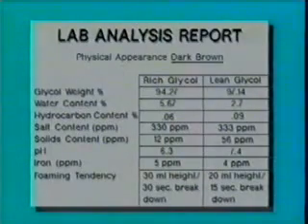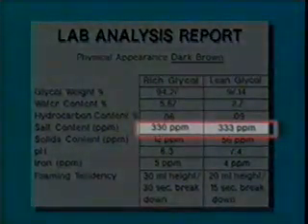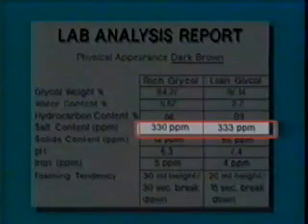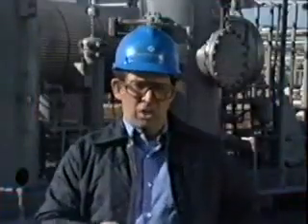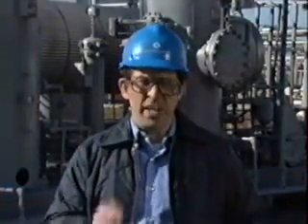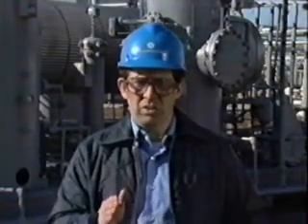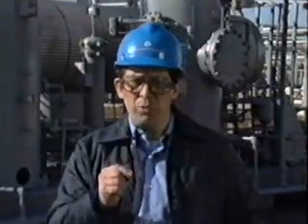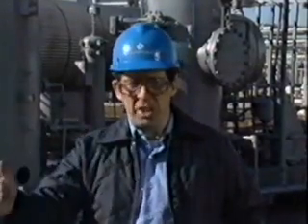Although the salt content of our samples is a little high, it is still in an acceptable range. Salt usually travels in the gas stream in a fine mist. Now, if the gas stream contains excessive salt, a coalescing or filter-type separator can be used to remove salt from the gas upstream of the dehydration unit.